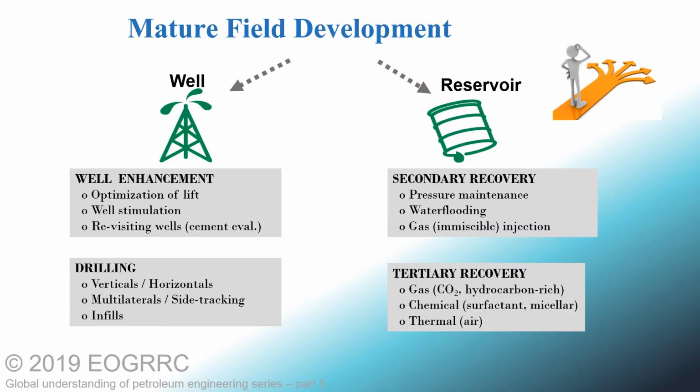Technologies applied to revitalize mature oil fields are based on either well or reservoir applications. Once the maximum number of wells that can possibly be applicable to the field is reached, well development practices such as recompletion, stimulation, treatments, optimization of lift, recollection of data, surveillance, and new entries are considered. Next, injectors for pressure maintenance or displacement are drilled, mainly targeting secondary or tertiary recovery.